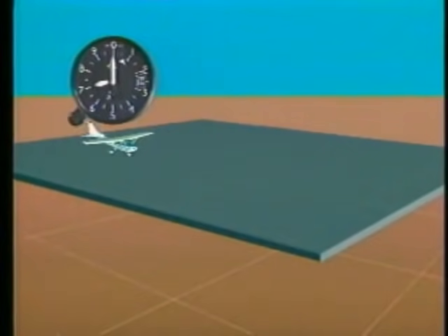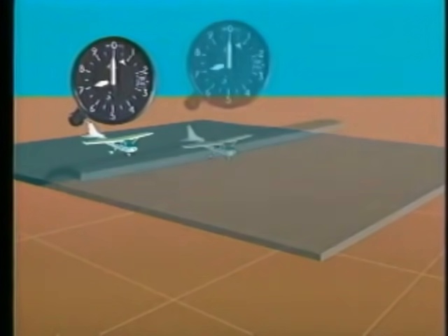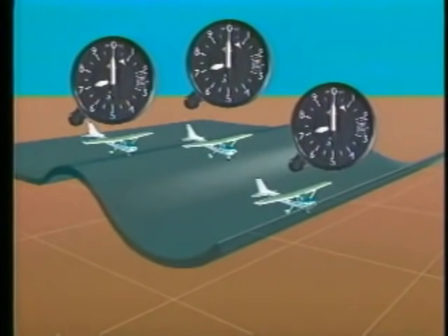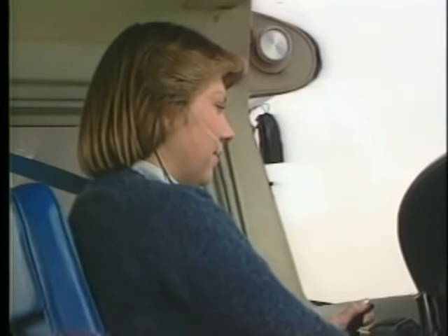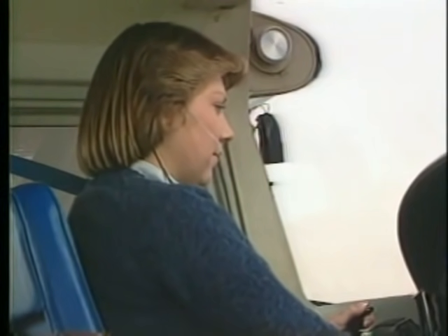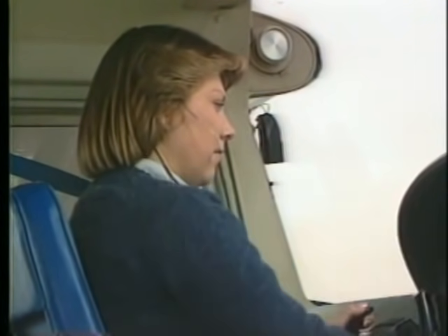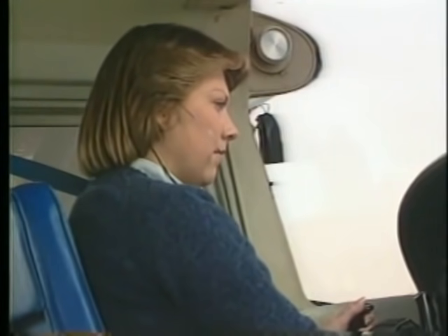If you didn't adjust your altimeter to the changing conditions, your actual height above sea level would be higher or lower than that indicated. Remember that as atmospheric pressure increases, your actual altitude is higher than that indicated. When the pressure decreases, your actual altitude is lower than indicated on the altimeter. To prevent the wrong indication, you should set your altimeter to the local altimeter setting. During instrument flight, air traffic control periodically provides you with the correct altimeter setting.